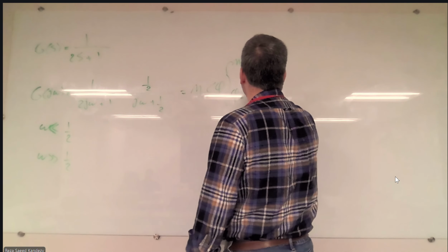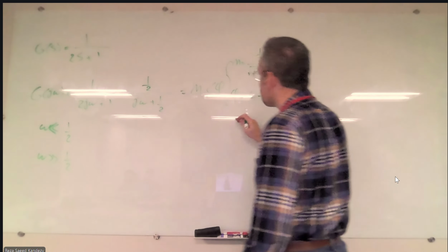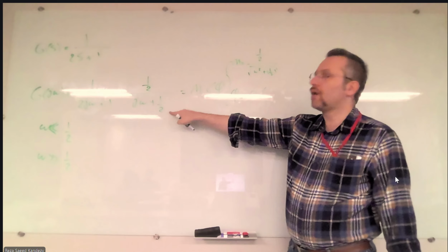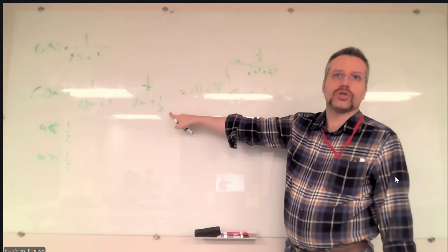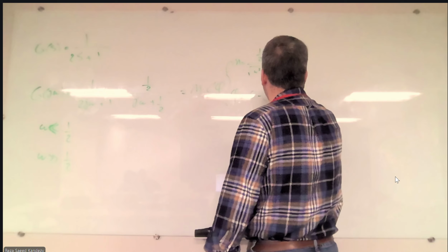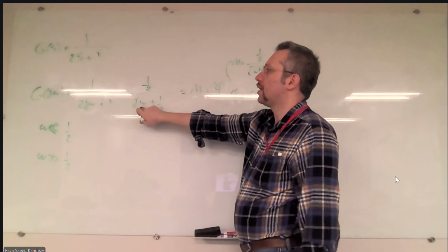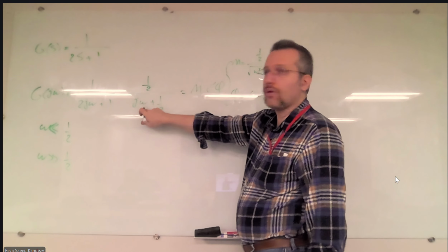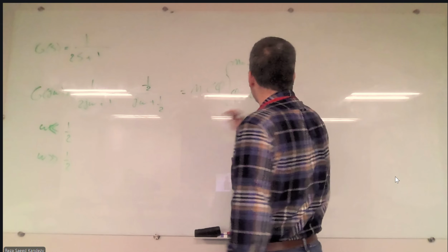So we have 0 for the numerator minus, we have one complex number here, so we are going to use the tangent inverse to calculate the phase of this complex number, which is going to be the tangent inverse of the imaginary value omega over the constant value, which is omega over 1 over 2, which is 2 omega.